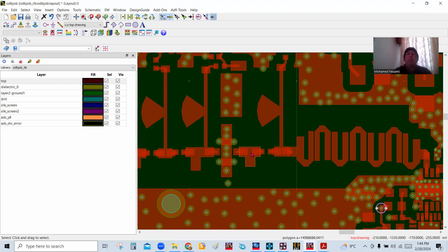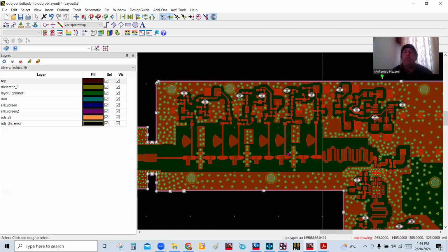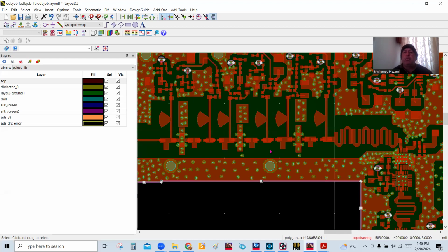So now here I am. I want to take this before we send it to layout, PCB fabrication and PCBA assembly. I want to make sure that I can run a quick check just to verify that nothing got corrupted during the layout process, because in the layout process, the RF engineer sends his DXF patterns of the microstrip work or the stripline work or whatever, and then the PCB librarian creates symbols for those, just like we did here.